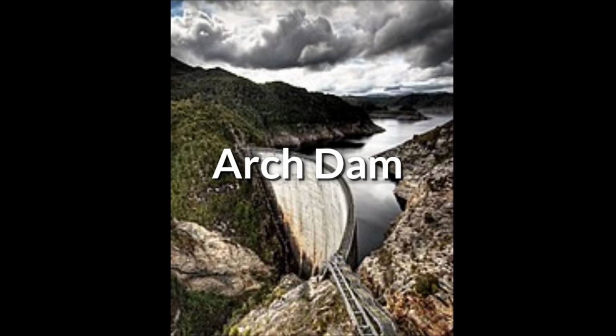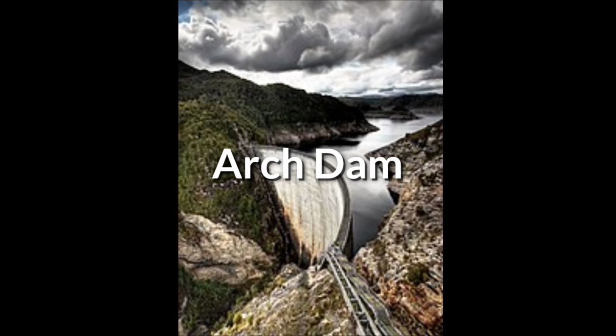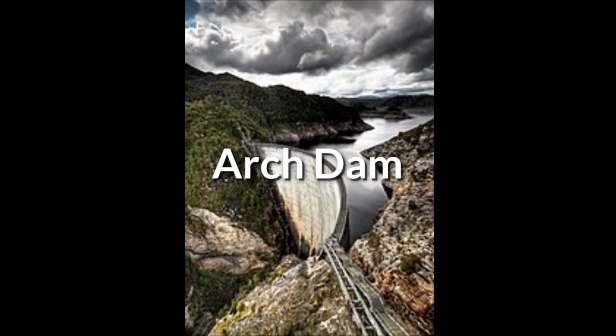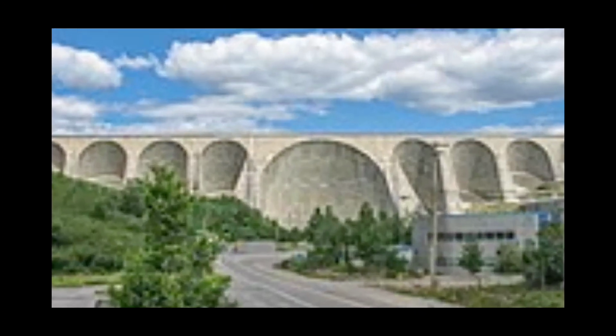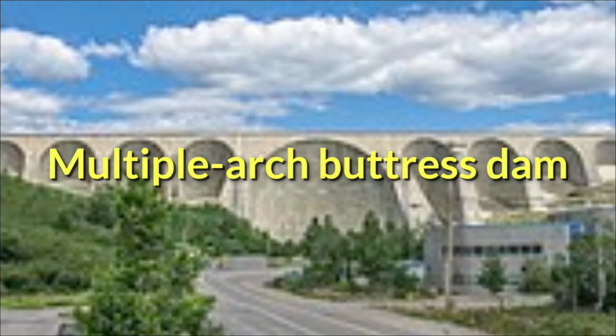abutments of the dam. An arch dam is most suitable for narrow gorge sections with steep walls of stable rock to support the structure and the different stresses. Since they are thinner than other types of dams, they require much less construction material, making them economical and practical in remote areas of any country.